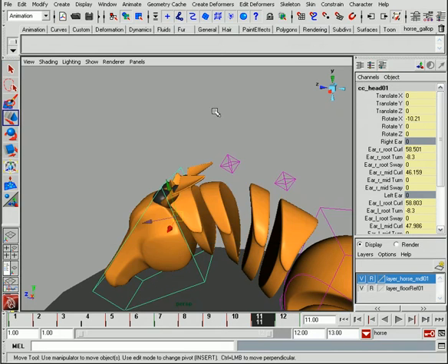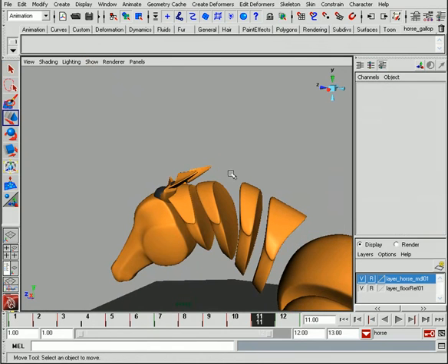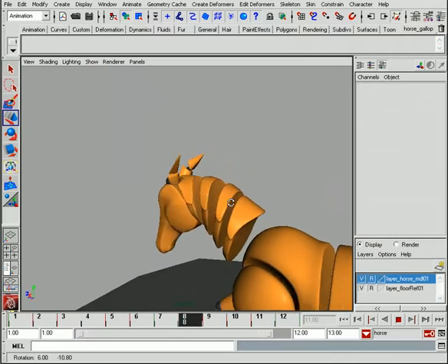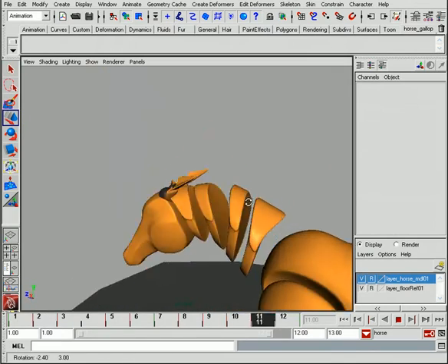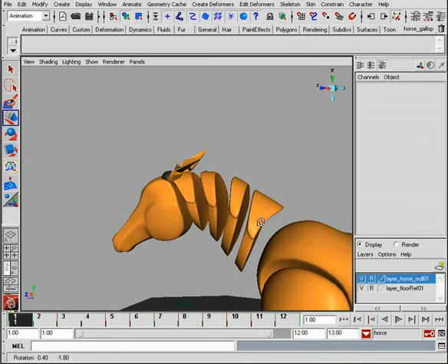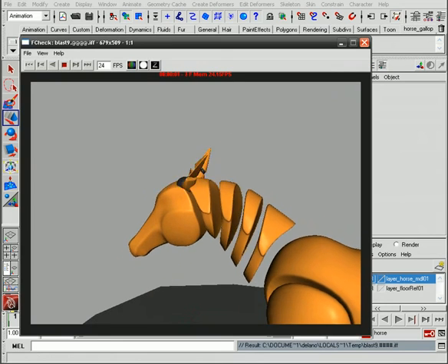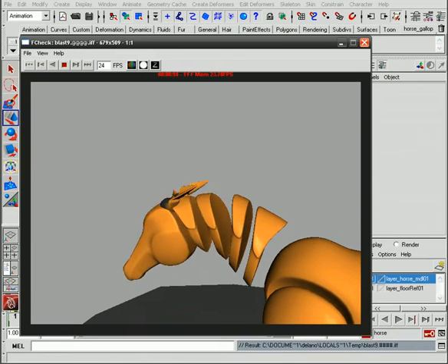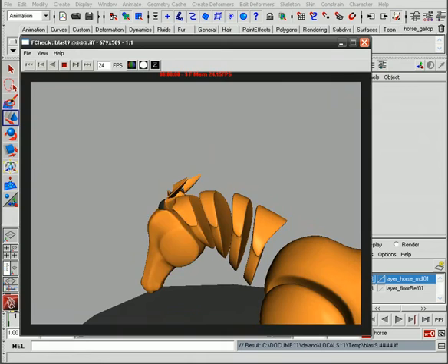When we minimize, hide our curves, and hit play, notice we get the ears slightly offset enough where the twinning is gone and we're getting some nice realistic looking motion in our ears. But of course, let's go ahead and check out a playblast of that to see the difference. Here it is. Great. So here we see again the benefits of utilizing copying and pasting. Look how much faster we got that right ear done rather than having to manually key it as we did with the left. And by sliding it just one frame off, it looks almost like a totally different ear. Okay, so that's the benefits again of using copying and pasting.